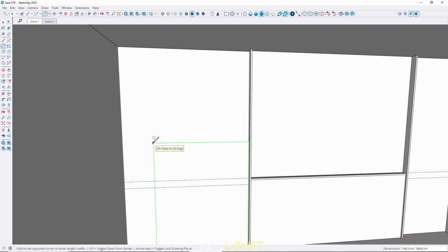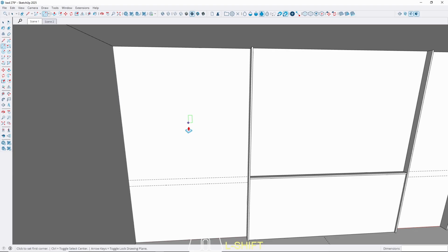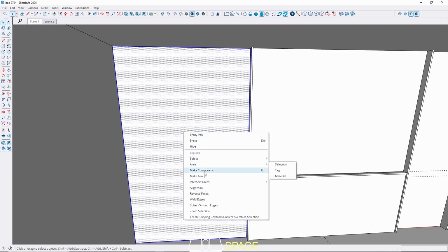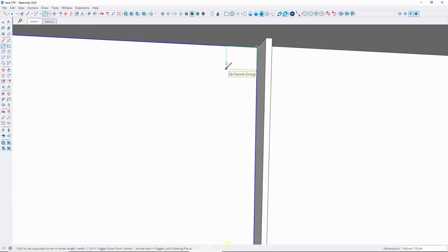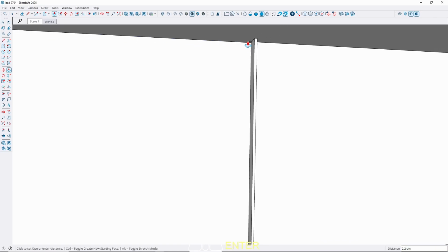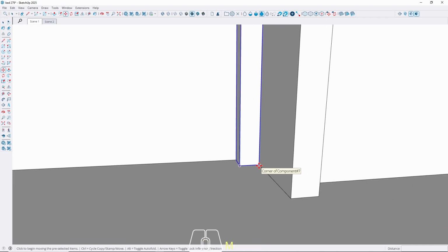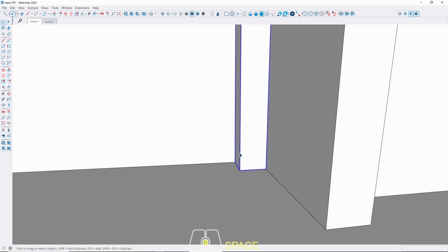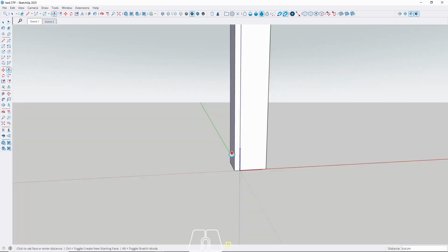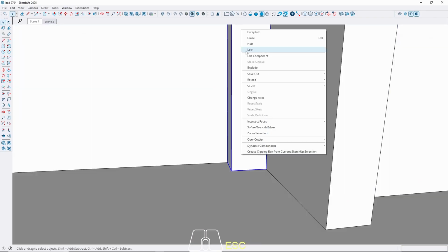Okay, let's make a base panel 1 centimeter, and then make a 2 centimeter square for a textured panel like this with 2 centimeter thickness. Okay, make it all the way to the floor. Make it component. Don't forget to group. Wait, it should be 2.6 because we're gonna make a gap, sorry, 3 millimeters from every side of the texture panel. 0.6. Okay, already component, good.